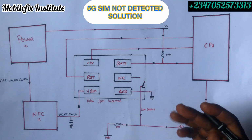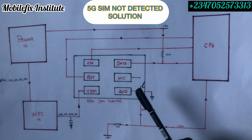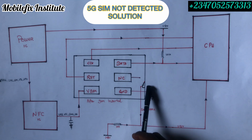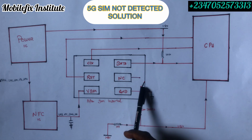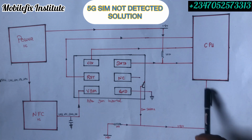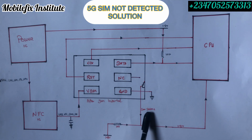So now let me explain the rest of the lines. Now we see here, this is our SIM detect. This particular line is connected to our power IC. It comes from our power IC. So it has a 10K resistor here, and it enters this SIM tray port and also goes to our CPU. Now this is called the SIM detection line.